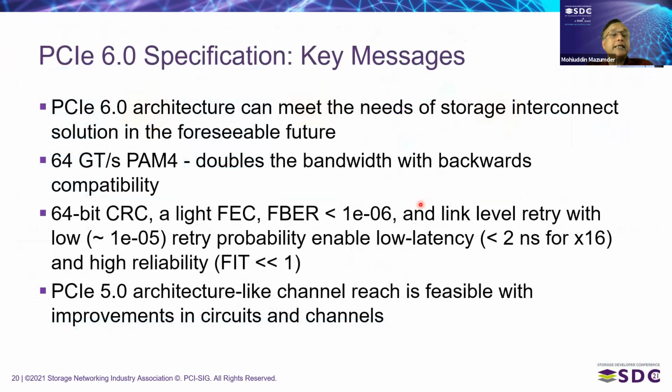So to summarize, in PCIe 6.0, this architecture can meet the needs of storage interconnect solutions in the foreseeable future. We see that this bandwidth provides not only data rate scaling; scalable width is another knob it has. It provides everything in a low power, low latency, high volume, and cost-effective way.